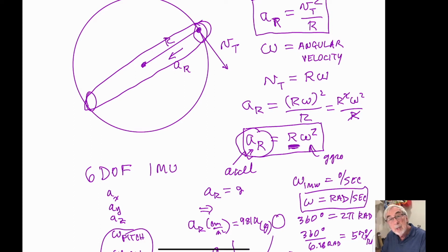How many measurements are you going to do? People always ask me that. How many data points do we take? And I always say, well, more than 3 and less than 1,000. It's a joke, right? So I want you to take about 200 to 300 data points. And you're going to say, whoa, that'll take us forever, okay? Now, it'll take you about 20 seconds to take 300 data points, because the IMU spits out data at 10 hertz. So every 10th of a second we get an omega and a reading, and the computer will take care of plotting all that data up.